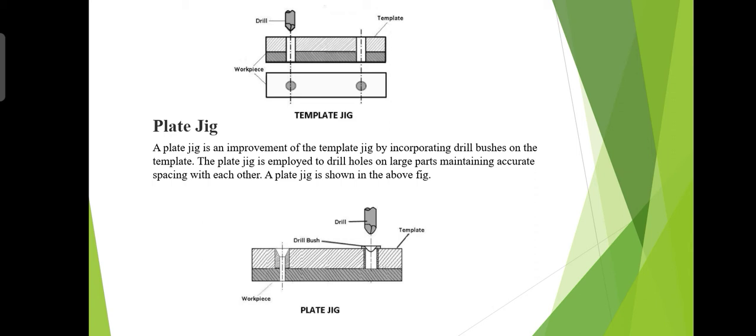Additional features are added in plate jigs by incorporating drill bushes on the template. Drill bushes are not available in the template jig. You can see it in the diagram. And the plate jig is employed to drill holes on large parts and maintain accurate spacing with each other.